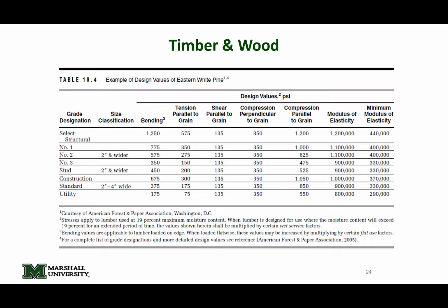For example, here's a beam. The beam sits on a sill plate. This is the reaction, so there's a reaction right here. We have to ensure that the wood element is not going to crush under that big support reaction. So that's a compression perpendicular to the grain that we're going to have to assess. If we're looking at columns, we're going to look at compression parallel to the grain.